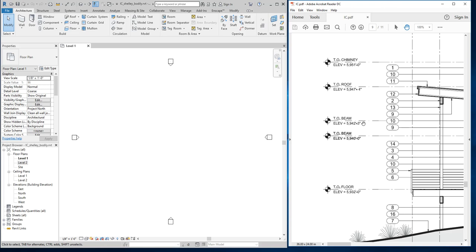There are two different ways to indicate height generally on architectural drawings. What they've done here is they've used actual elevation above sea level, 5,942 foot 3 inches above sea level, right? Another way that you'll see this indicated in architectural drawings is this will be elevation 100, and then if this is 10 foot 3 inches above the 100 mark, it'll be 110 foot 3, right? So this is probably the more accurate method of going about it, looking at the survey and figuring that out. But we have to do our math and figure out the difference between them.